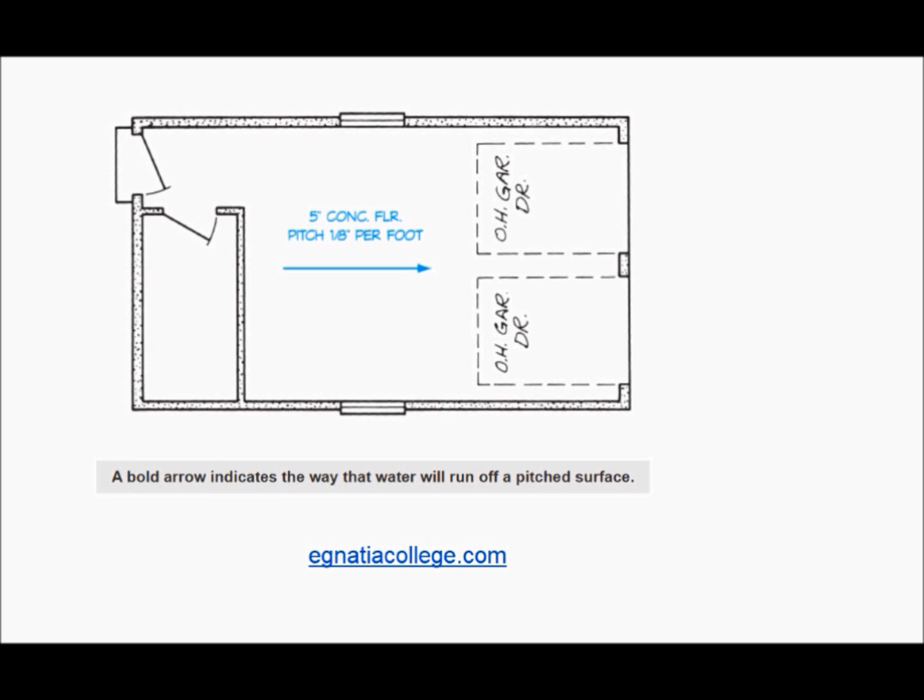These installations must be made so that they do not reduce the structural integrity of the concrete slab. An oversized raceway in the concrete slab may cause the slab to crack and settle unevenly. An electrician should be present during concrete placement to observe and correct any damage to these electrical raceways.